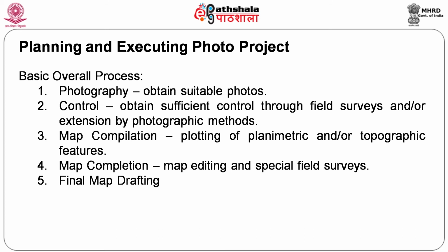What are the other methods, or what is important to execute? How do you execute a photo project? First thing is to get a suitable photo and take control points. This is a very important one. Taking photographs is one part, the other is to rectify the data. With satellite data, at least, the advantage is that you will know the object you are taking, because satellites themselves know their position.